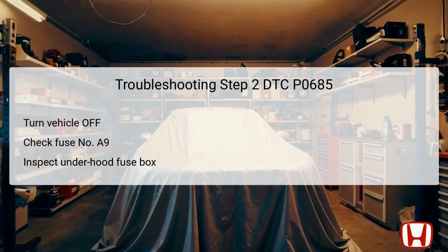If the fuse is found to be intact, you will proceed to the next step in the troubleshooting process. However, if the fuse is blown, it indicates a potential short circuit in the wiring. In this case, it's essential to repair the short circuit and replace the blown fuse before continuing with further diagnostics.